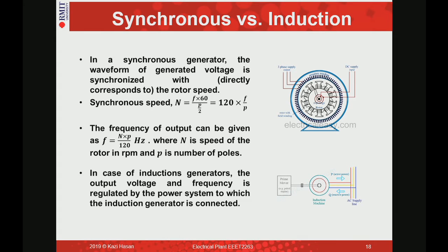That is the synchronous rotating speed of the magnetic field with respect to the rotor, isn't it? Omega s minus omega r over omega s. So the slip is the difference between the speed of the magnetic field and the mechanical rotation. But in a synchronous machine, the rotor is rotating at the synchronous speed. So just remember that difference between these two.